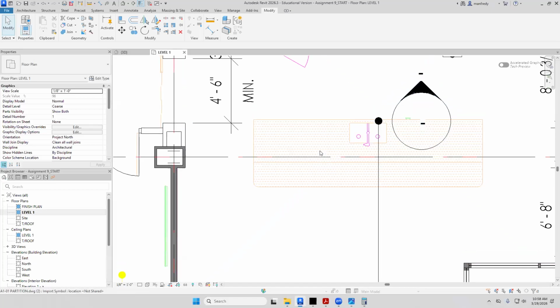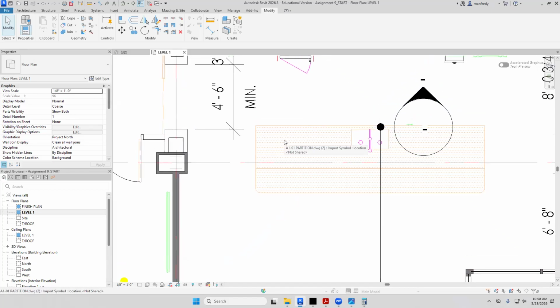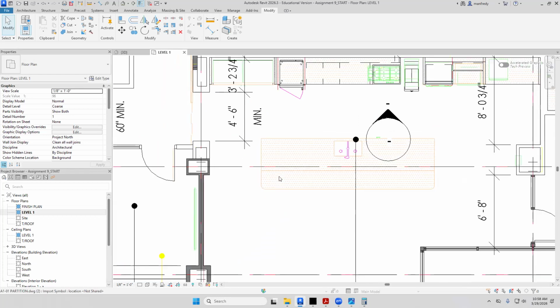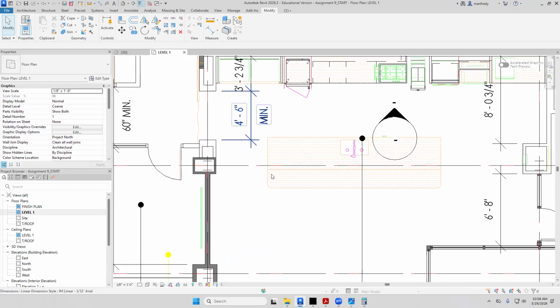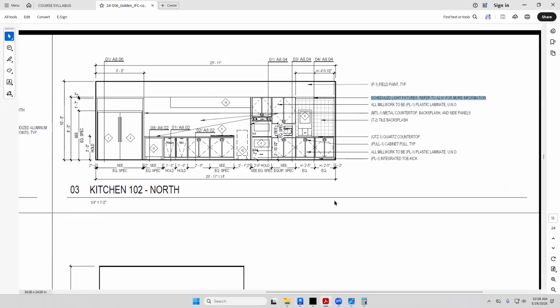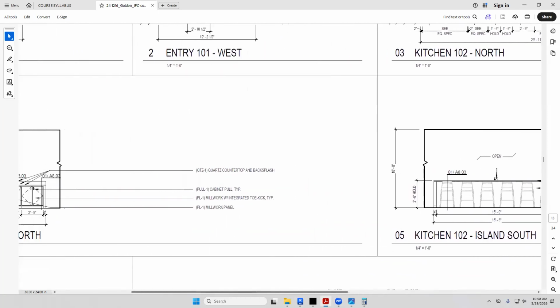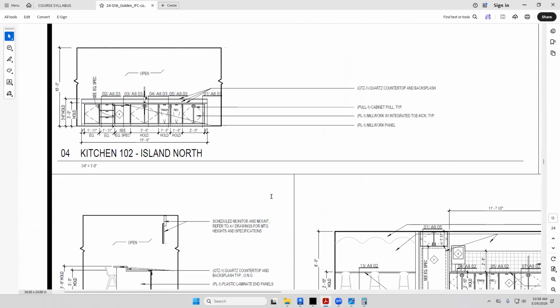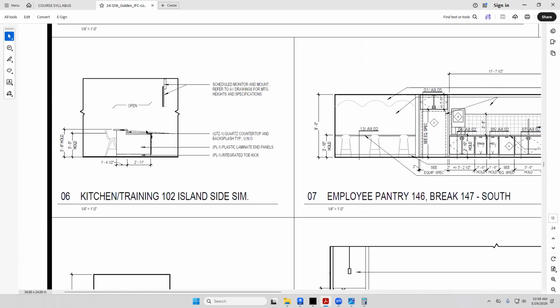on the flip side. So to draw this, what I'll recommend you do is draw it from the side, because the side view will let you draw what the elevation looks like of this wall that's stepping down. So when you draw elevation from the side, it's best to use a reference plane, because then I can draw on a reference plane, which acts like a piece of glass. I can sketch out the side cabinet, or the side wall rather, and then I can use it to create the look I'm after. So this is the side view here, what we're looking at.